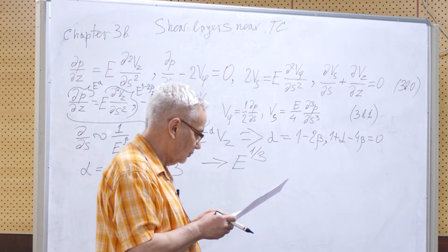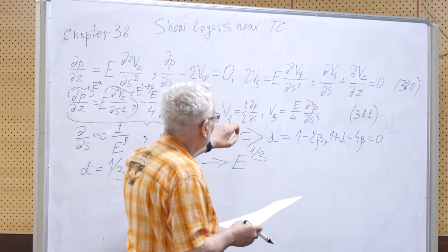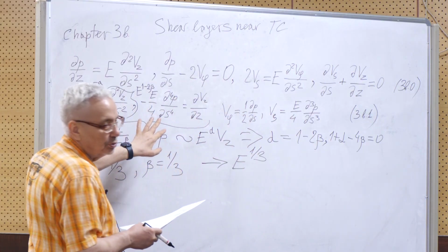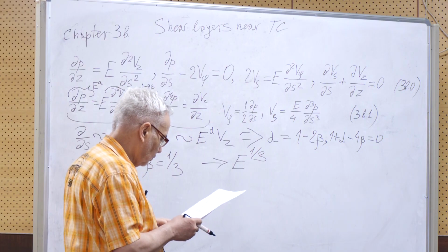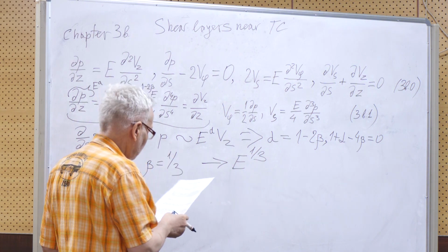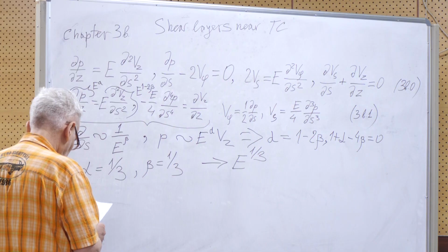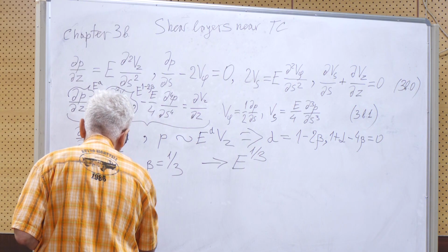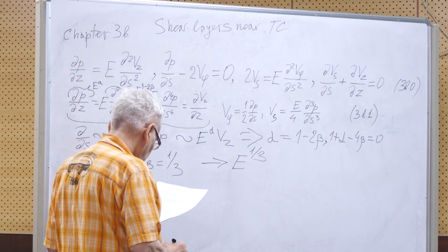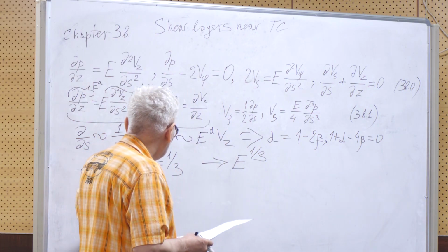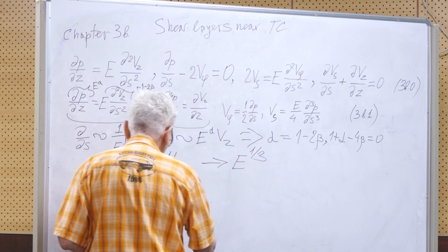Accordingly, the solution of the first two equations from 1, again I stress, we reduce the initial system from 4 equations and 4 functions just to 2 equations. So the solution of the first 2 equations can be thought of in this form. Actually, if we have pressure and the z component of velocity, we have a complete solution. So we just keep these 2. The form of the solution we are looking for is Vs and P. Let's make it like a 2-dimensional vector, just for simplicity, because they have a common multiplier.